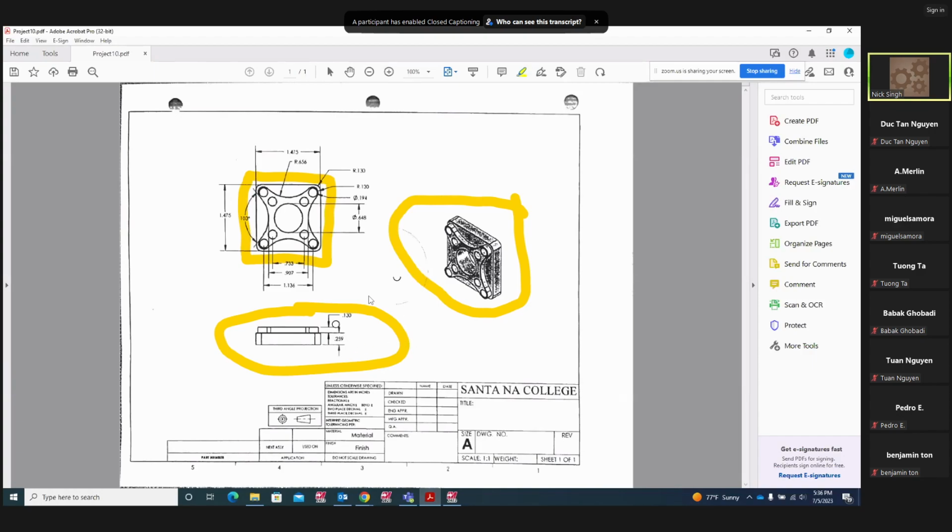We're going to create this geometry first. If you look at this geometry, guys, this geometry has to be something like this. We're going to create a diameter of the part like this first. And this is going to be my center line. This is my zero over here, right on zero. So I'm going to create this. I'm going to face this part, then I'm going to turn the diameter and this diameter. Then we're going to create this geometry right here on the right side plane. And then we're going to use the live C-axis tooling and create this contour right here. And then we can face drill that. And we can drill this right in the center. That's going to be our regular drill.